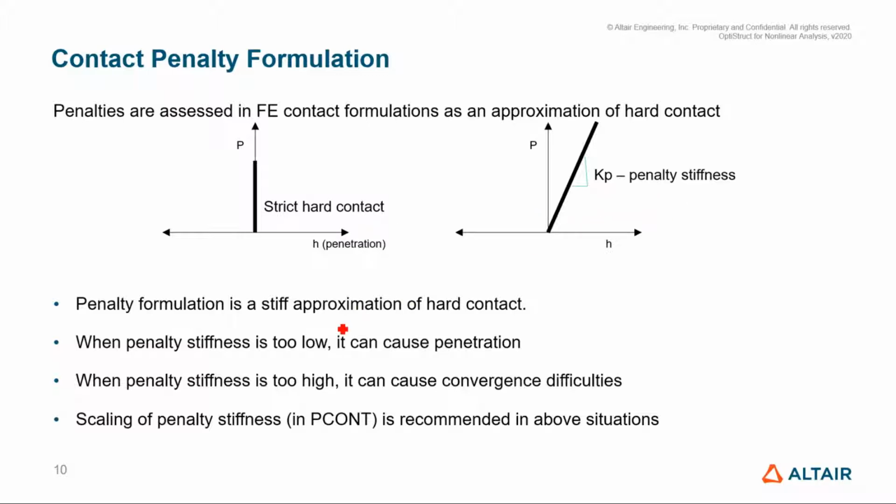You can actually change the stiffness of that penalty here. Okay, so you can put it lower. With that, your slope won't be so steep like this, right? So there will be a slope to it, and you can also adjust the penalty stiffness here. So there are a few ways. One, you can leave it at default, okay, or you can also put penalty stiffness equals to high or penalty stiffness to low. Okay, so those options are available, or you can also directly put in the value that you want. Okay, so we'll talk about this stiffness later, right?